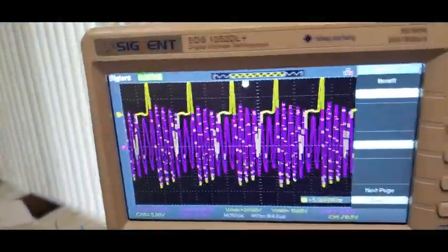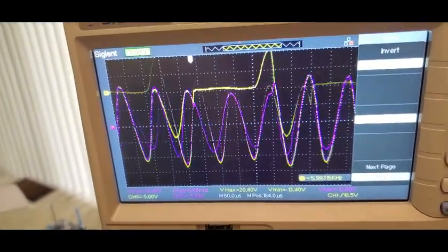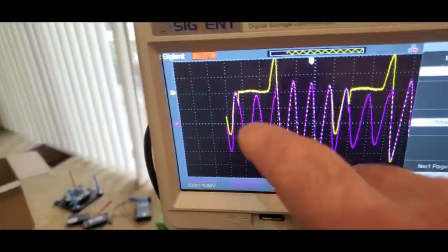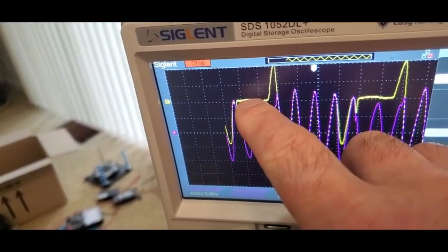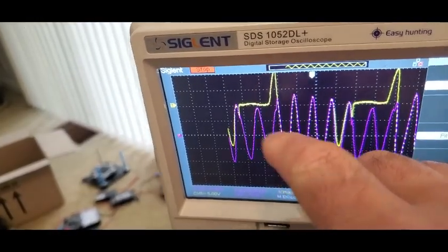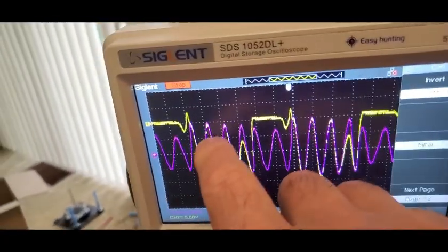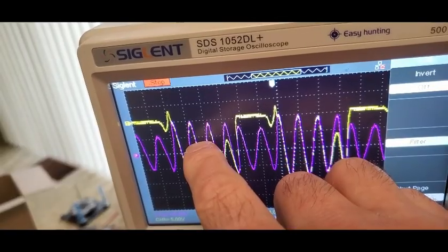And you see, this is what we were seeing. And let's zoom in a little, and I'll show you what really caught my attention. It's this part. This is where this cap is oscillating in voltage while you're charging the cap before you've done anything. And let's change the timing a little bit. So here's a pretty good example. So see, this oscillation is different than that oscillation.